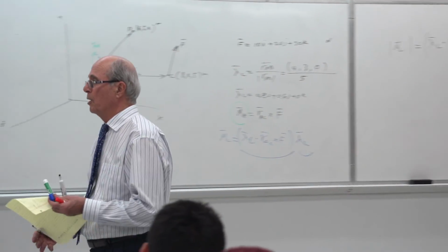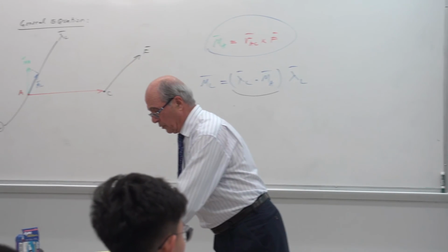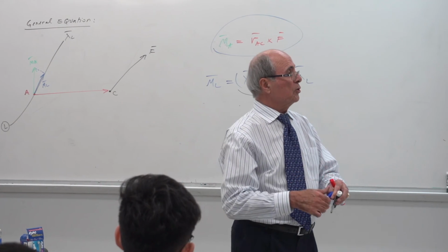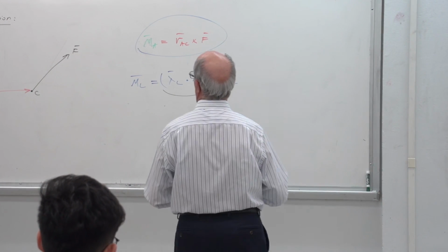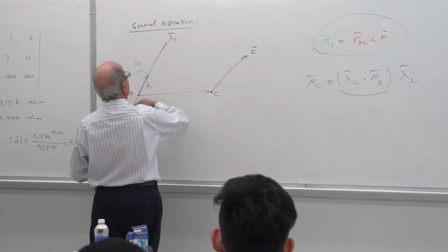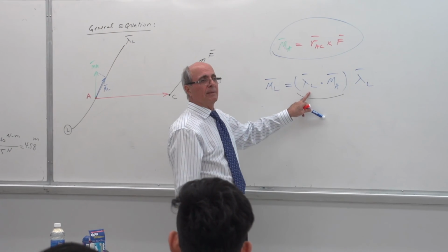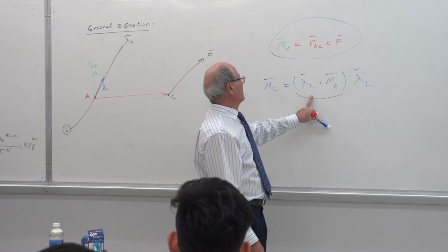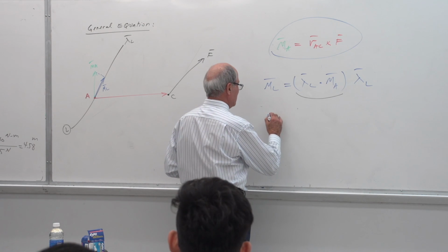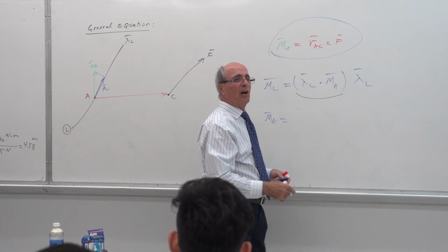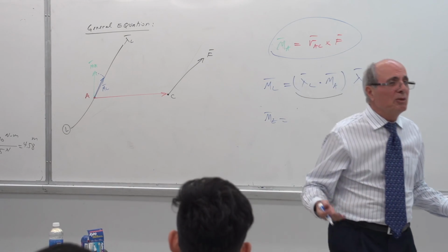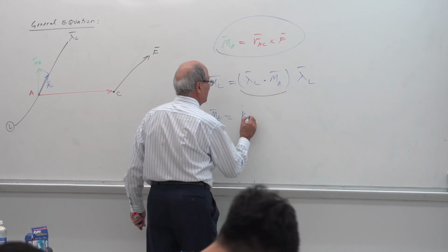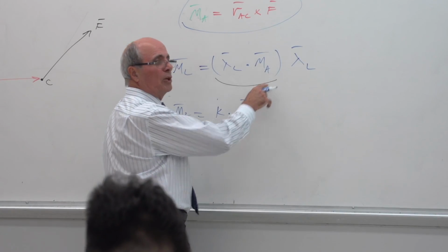However, give me one more minute, an extra minute. Now, remember earlier I said how to calculate the moment about a line? We could use that. Actually, go home, check this one. If this line happened to be the z-axis, what happens to this? What is the lambda of the z-axis? MZ becomes equal to, what's the unit vector along the z-axis? It is k. Very good. So k dot product of MO, because O is on the z-axis.